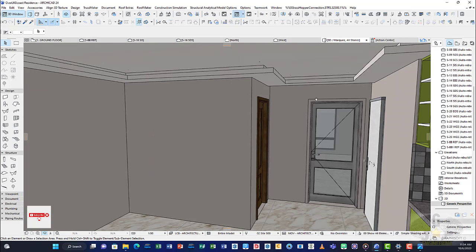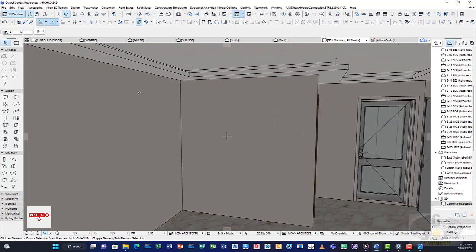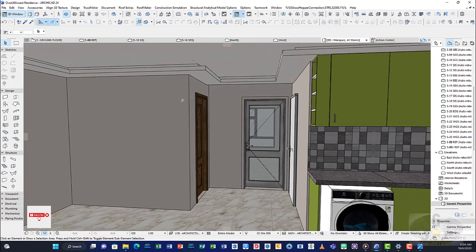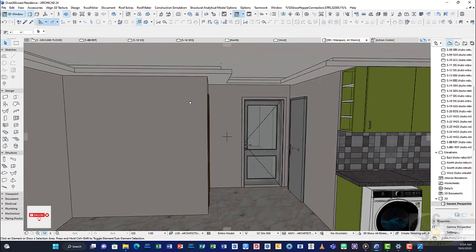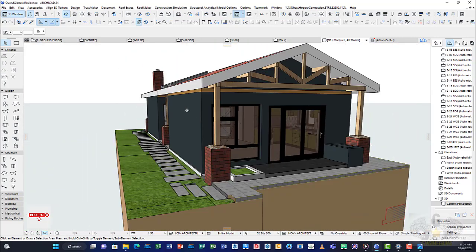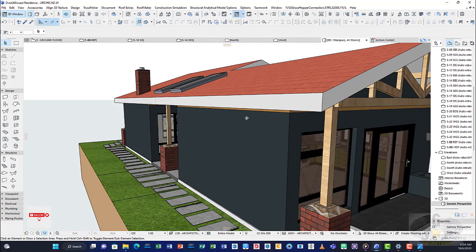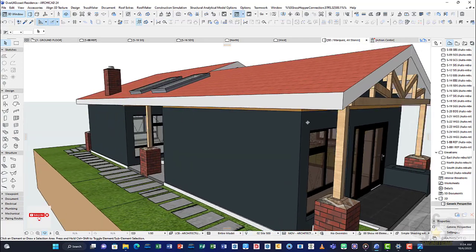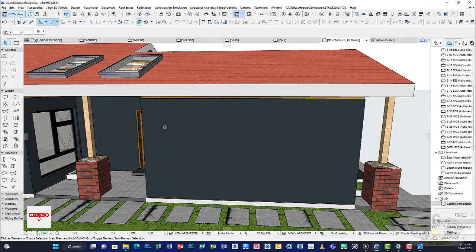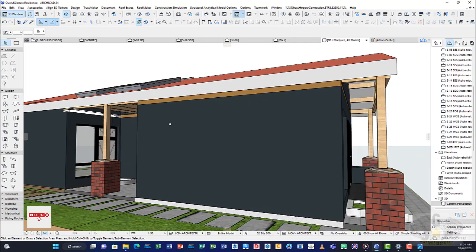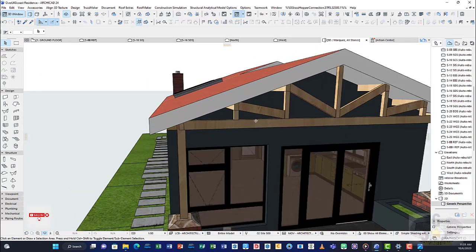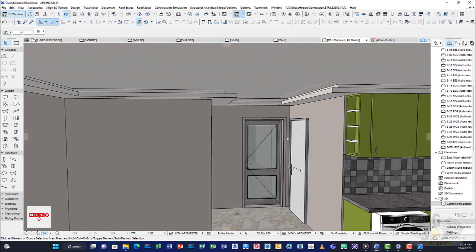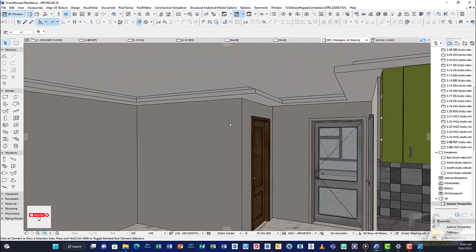So installing vents in all the walls will take that heated air out, and when the wind blows, it will allow the entrance of fresh air as well, preventing the entrance of insects. You never know, it depends on the environment where the project is going to be. I'm just putting countermeasures in place, in case.